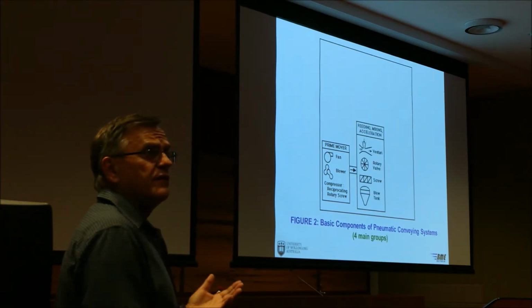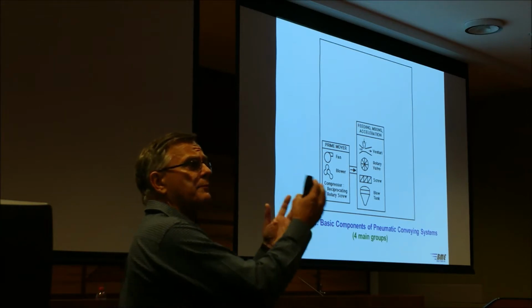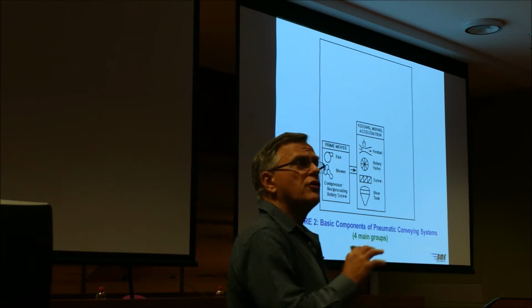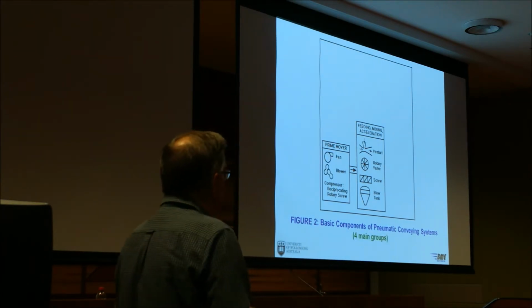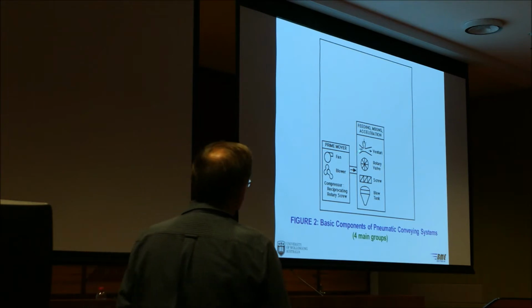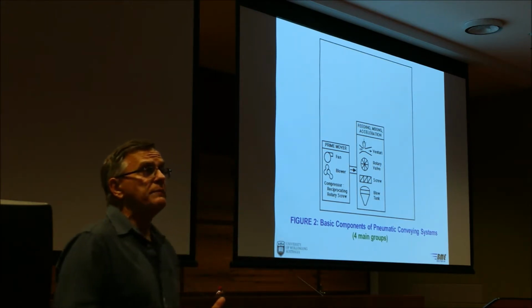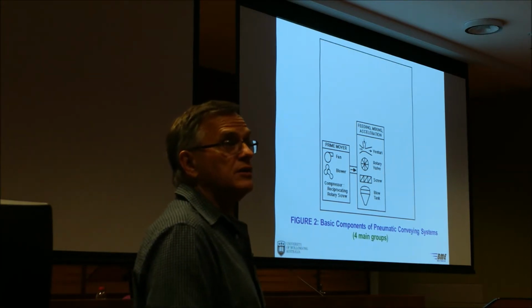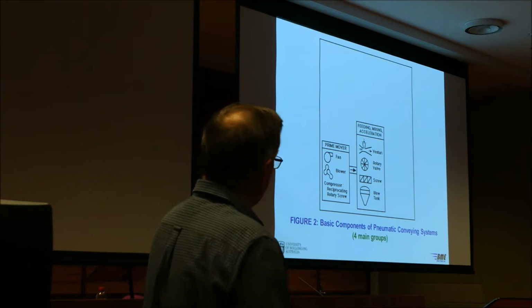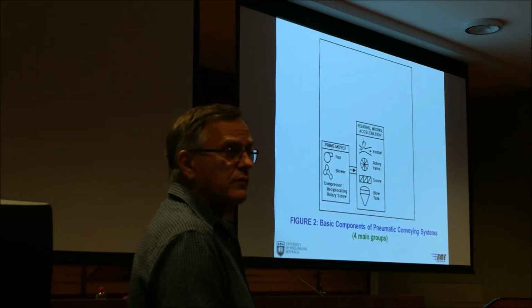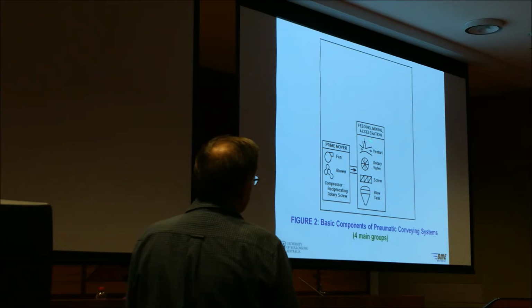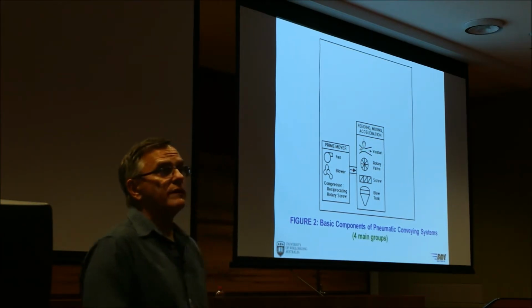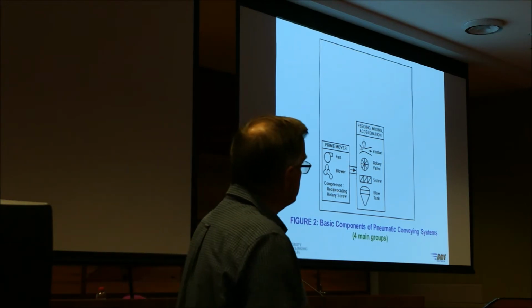Then we go into selecting our feeder. How are we going to introduce our powder, our bulk material, into the pipeline? How are we going to feed it? How are we going to control that feed rate or flow rate? Different devices available. We can use a Venturi meter, which is nice, hasn't got any moving parts. It's like a suck blow system. You can design one of these using the old Bernoulli's equation. So if you put air through a converging diverging nozzle, you design that properly, you'll actually get a vacuum at the throat, and you can suck in particles at that point. So it sucks particles and then blows them.